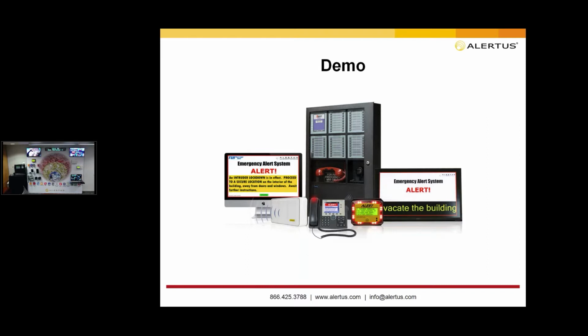instead of having to go to the fire panel, look it up, then possibly even look at the, because the fire panels, what we didn't talk about is that a lot of fire panels have restrictions on the characters that they're able to use on the description. And what that limitation is usually at is about 24 characters. So what a lot of people have seen, if you're fire technicians out there or you've noticed fire panels, is that you'll see that there's a lot of acronyms that need to be deciphered, and not all acronyms are the same at every location. I mean, I've seen NURS that stands for nurses station or nursery. It really depends on whether the person knows what that is or not.